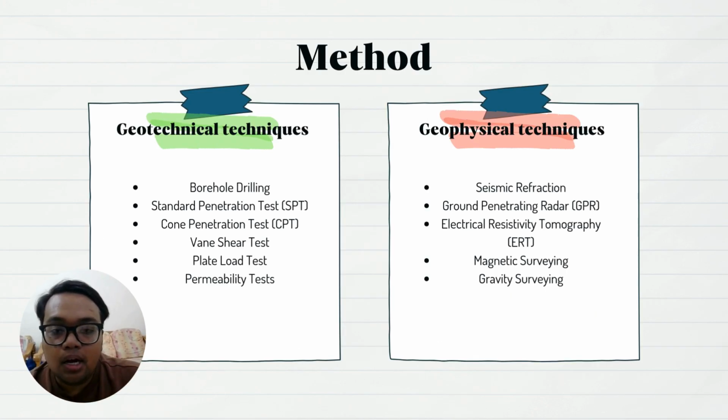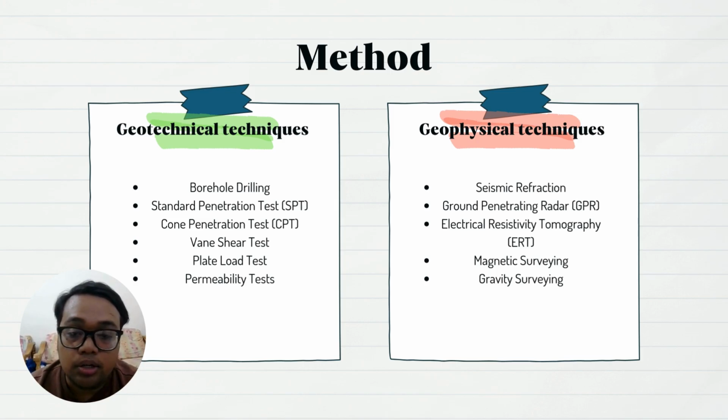Okay, for the next part, I'm gonna explain on the methods that are commonly used in the industry for both the techniques. For the first one, which is geotechnical techniques, there are few techniques that we use. One of it is borehole drilling. Second one is standard penetration test (SPT). Third one is cone penetration test (CPT). Next is vane shear test. Next is plate load test, and lastly is permeability test.